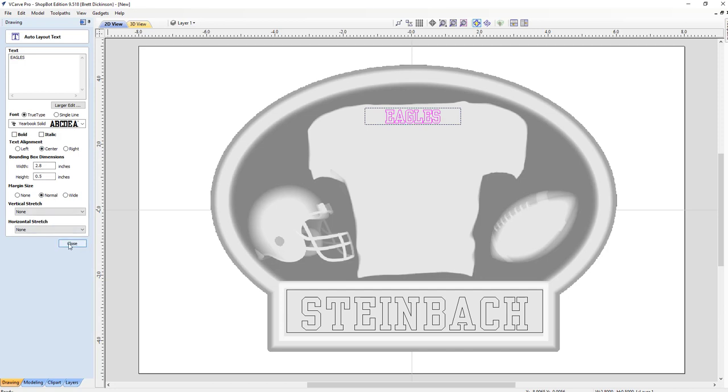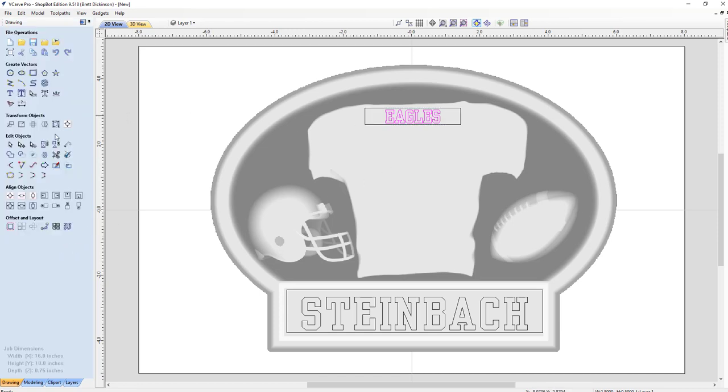And then I'm going to do the horizontal stretch, stretch spaces. That's going to get me what I want. So I'm going to go in here to Edit Text Spacing and Curves. Same thing, hold my Shift key down and get some space in there. Again, right over here, get some more right here, and get some more here.